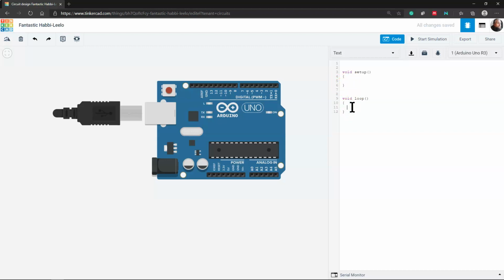And when the controller starts up for the first time, so saying that we've clicked Start Simulation and the Arduino's given power and it's running, the first thing that happens is that the setup function is actually called and any code that's in there is executed. So this is always things like specifying what your GPIO pins will be, what your variables are set to for initializing, and any kind of setup features that you need. Once this is done running, nothing else will happen until this is done running. So you want some quick actions in here.